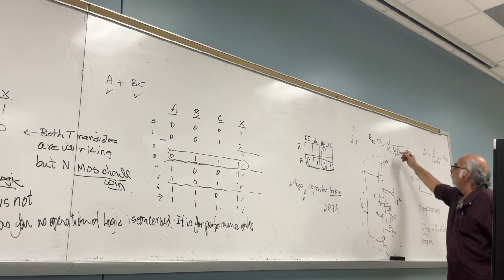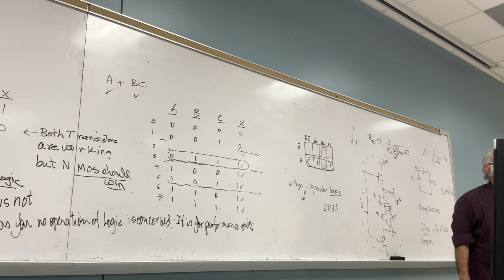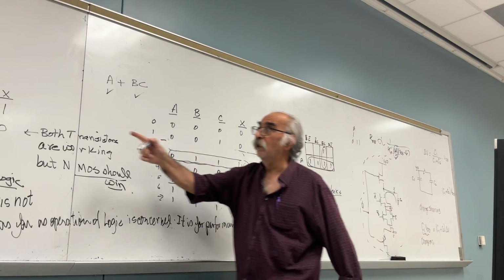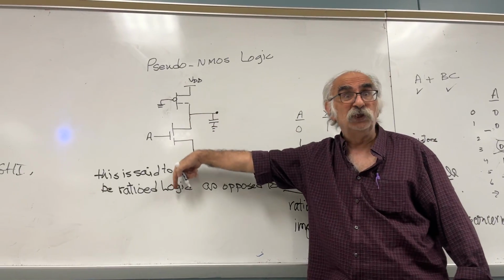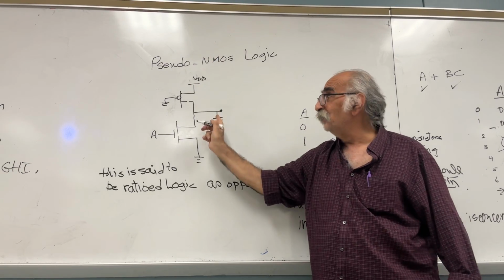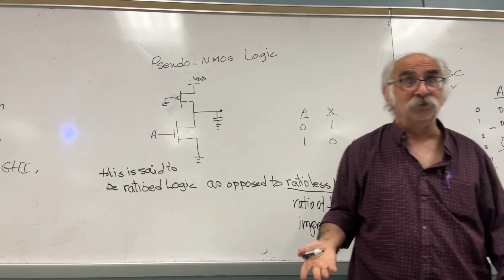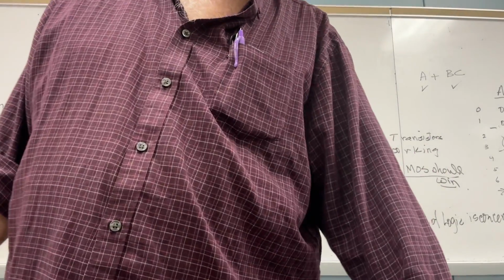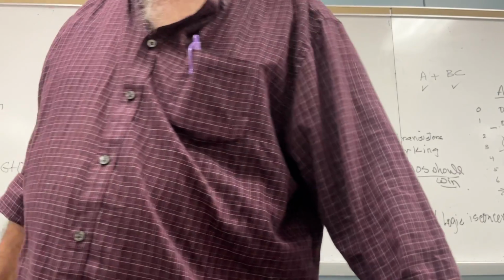Do you see what W over L is? Where, in the numerator or denominator? Which means what? I want to make W over L large, so that the resistor becomes smaller. Which means this one prefers to discharge rather than charge. Why? The current always chooses the path with the least resistance. Did you lose me? Everybody?